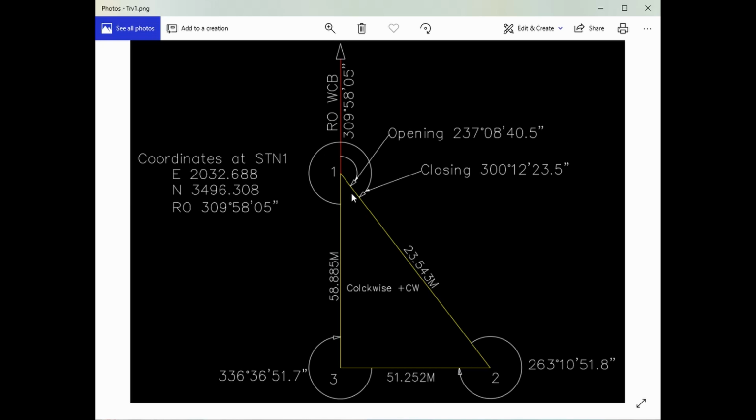From the unadjusted coordinates, when we get to the end here, we can get the true misclosure in eastings and northings. From the true misclosure in eastings and northings, the app will then calculate the Bowditch distance corrections and will apply them to the unadjusted coordinates to give us finalised Bowditch corrected coordinates. Basically that's how the app works. In my opinion, this is probably one of the easiest and quickest ways, and probably one of the most accurate ways, of doing a closed traverse using the Bowditch correction method.